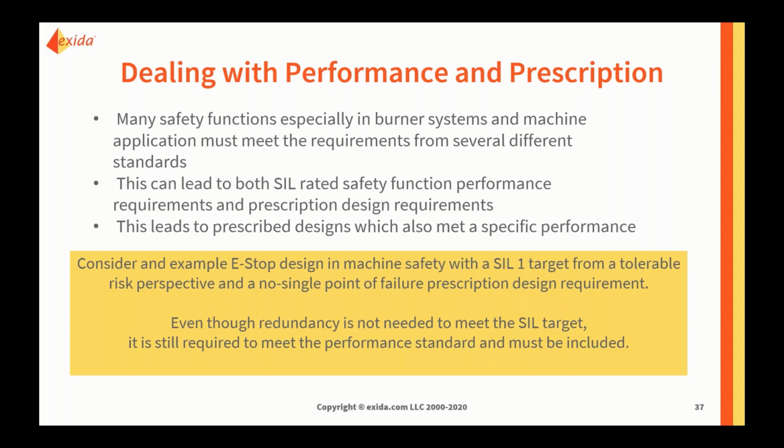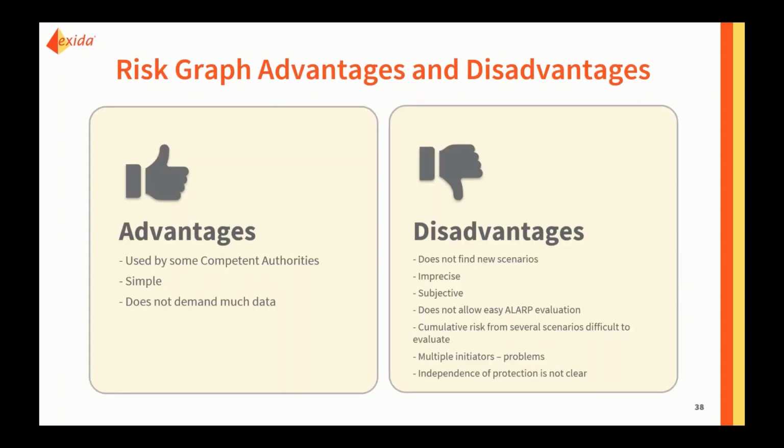So we've now talked a fair bit around the aspects of layer protection analysis, some of the simplified approaches to that are present in the risk graphs in the standards. And let's look at these and sum things up. So risk graphs, again, very basic, very simple, do not require a lot of data, absolutely sitting in their favor.